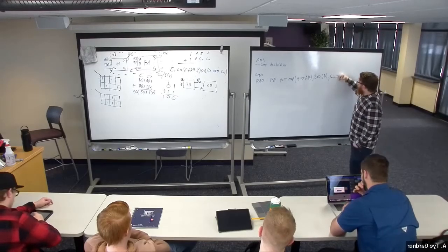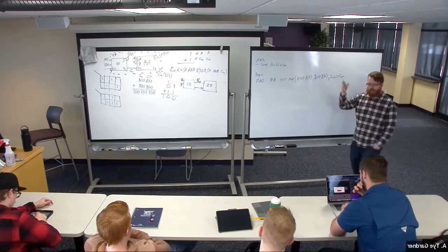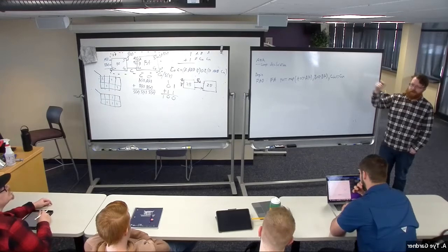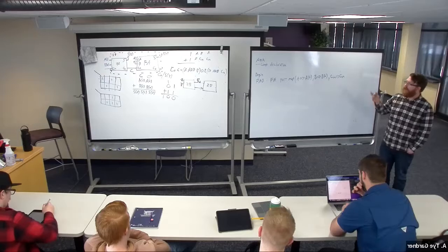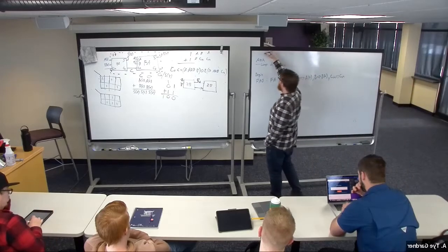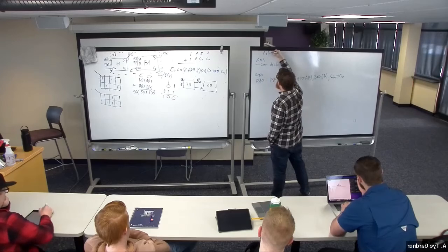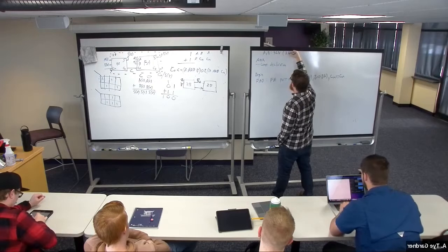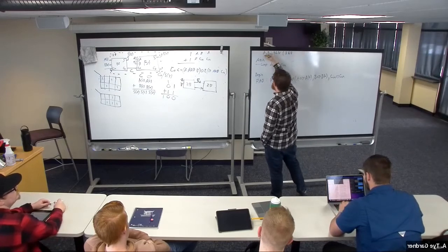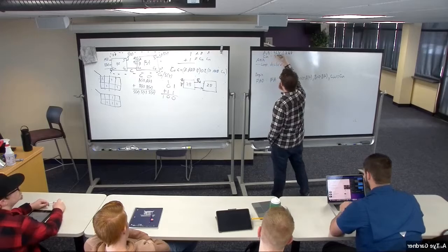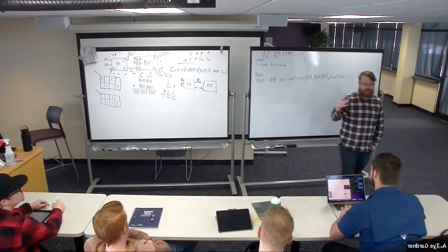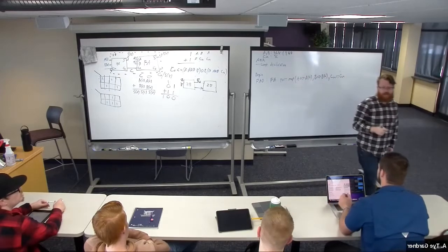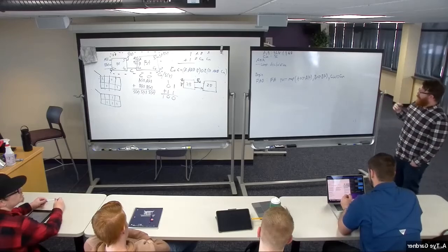If not, then I want a port called Cn. Now I can use this 2-bit adder as a component in a 4-bit adder. Do you see the difference? This one is going to have ports A, B, their standard logic vectors of 2 down to 0, and Cn, which is just standard logic, which doesn't have a vector, so it doesn't need to size. Oh, sorry, not 2 down to 0, 1 down to 0, right? Because it's 2 in size or 0 indexed. Okay, so there we go.